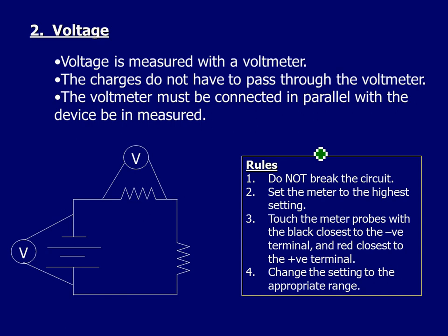So, with our digital voltmeters, we will set our devices to DC. We will turn it to voltage that's greater than about 7 or 8 volts, because our devices are going to produce about 7 or 8 volts. So I'm using a 40 volt setting here. Okay?